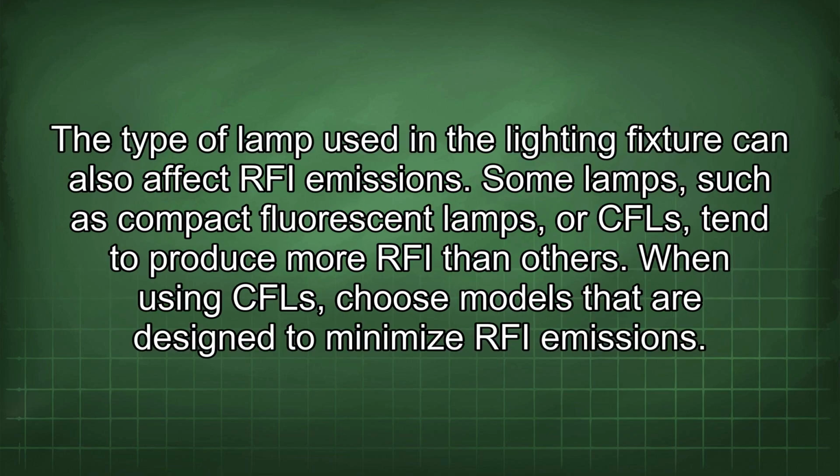The type of lamp used in a lighting fixture can also affect RFI emissions. Some lamps, such as compact fluorescent lamps, or CFLs, tend to produce more RFI than others. When using CFLs, choose models that are designed to minimize RFI emissions.